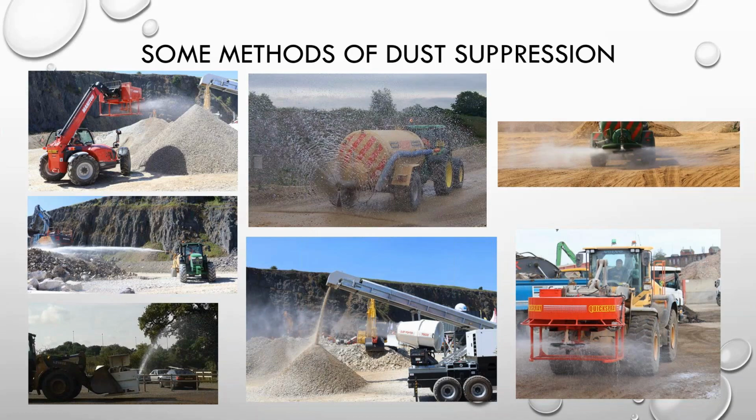Once we have discussed some of the options available, we will then look at some on-site dust issues and discover which application could be best for that site. The versions we will discuss range from high volume, site drenching water applications through to far more water efficient mist applications, all with their own unique characteristics. Accompanied with a thorough assessment of site requirements, the correct type of dust suppression application in the correct situation can be very effective.